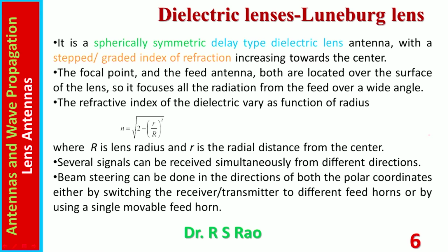It is a spherically symmetric delay type dielectric lens antenna with a stepped or graded index of refraction. This index of refraction increases towards the center. Here the basic point is it is a sphere. It belongs to delay type lens. It is a dielectric lens. The index of refraction of the lens medium increases towards the center.